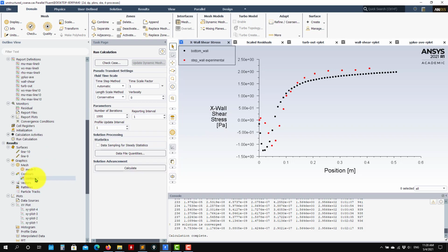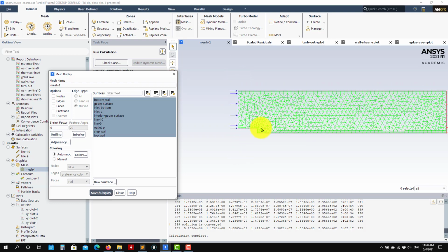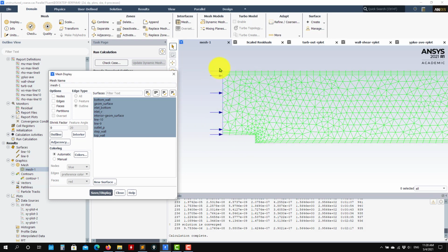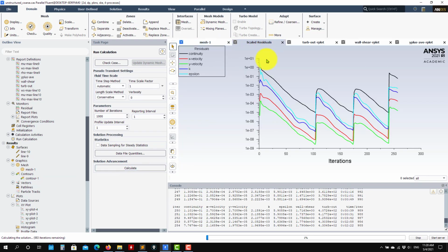So what we're doing now is that at the inlet everything is uniform. Previously it was this developed profile. What I did to get that one is take the inlet and a longer section, let the simulation run in that straight section, get the profile at the outlet, and then interpolate it here. That is strongly recommended. Having a fully developed profile is more realistic. So let's run now using the uniform inlet.